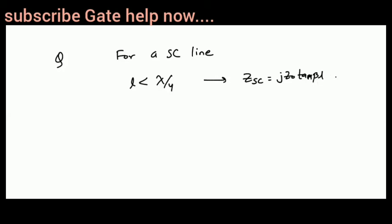So for a short circuited line, if the length is less than lambda by 4, then how can you use this transmission line? What will be the behavior of this transmission line? For L less than lambda by 4, its impedance ZSC is j Z naught tan beta L. This will be positive, so this will be inductive. So for L less than lambda by 4, a short circuited transmission line can be used as an inductor.